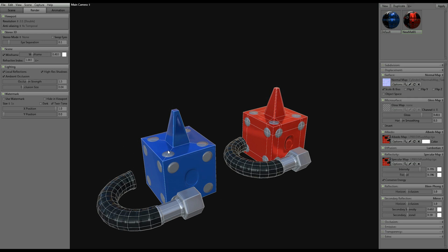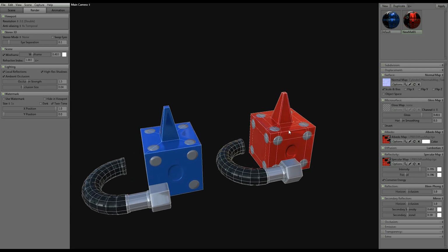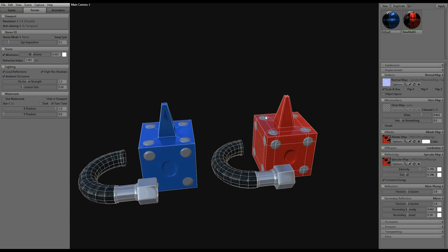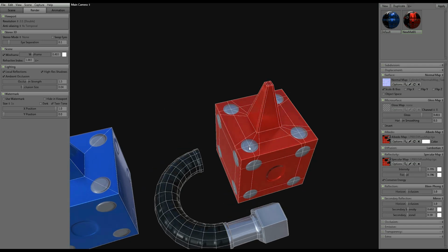On top of that, everything is set to one smoothing group. So what I'm doing is I'm asking the normal map to take care of all the smoothing and the shading for that, and it's too much. So how do I fix this? One way, like I showed you, is adding supporting edges to the low poly mesh.